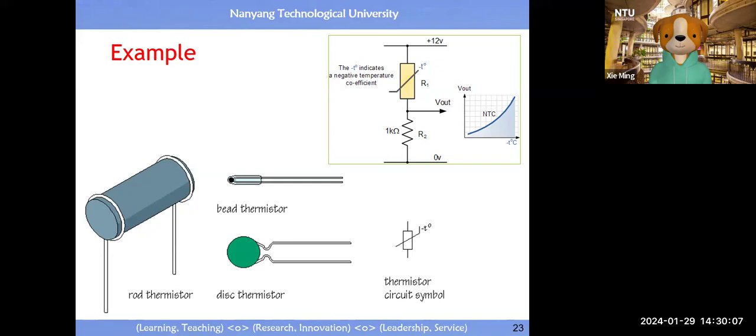But these kinds of non-linearity can easily be rectified by calibration, right? So you do a calibration, you have an equation to rectify this non-linearity. So mathematically this is not an issue. Once you are able to convert temperature into a digital number, always remember you need to do calibration.